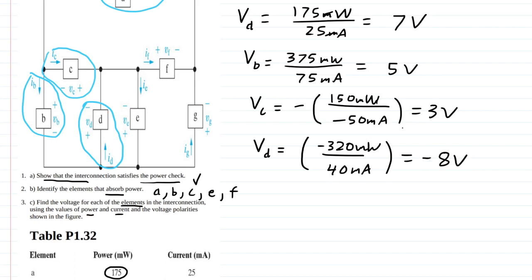Now once again, minus just means that the voltage, let me use a different color. The voltage over here is 8 volts lower than the voltage over here on the minus side. Because the voltage is always relative, so basically you could flip this around and say that if this was the plus and this is the minus, then it would be 8 volts across.